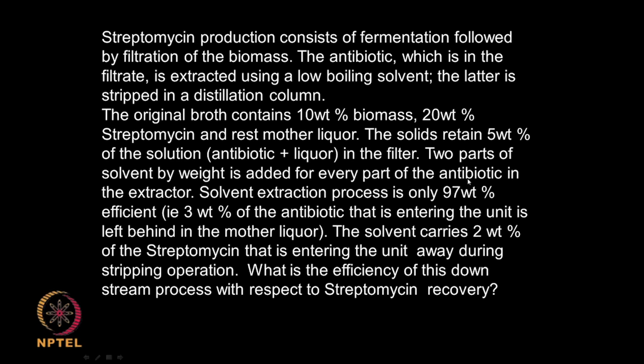Now, you are adding 2 parts of solvent to recover the antibiotic by extraction. The solvent extraction is not 100% efficient, it is only 97% efficient. That means 3 weight% of the antibiotic that is entering the unit is left behind in the mother liquor. It is able to take out only 97% of whatever is entering, and the rest of it is gone in the mother liquor.